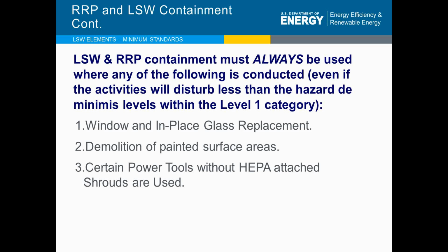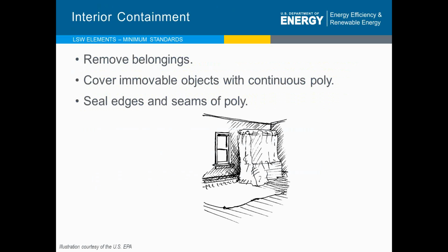Demolition, if we're just ripping out a fairly large area, it's just a lot more destructive, and we have to be careful about that. And then if we have certain power tools that we're using that are not attached to a shroud and the debris is not collected in a HEPA vac, these are greater considerations for more containment.